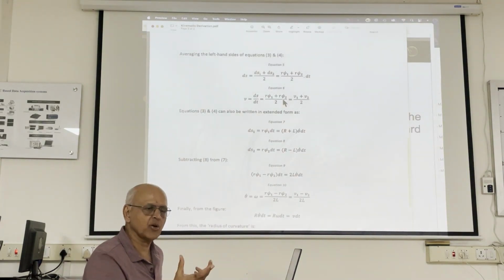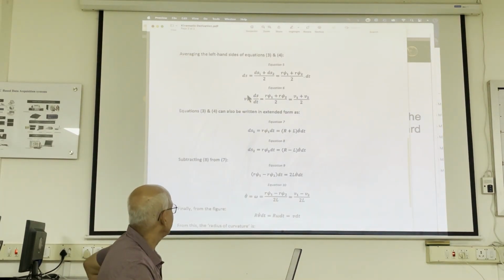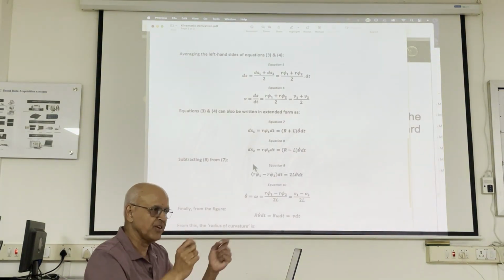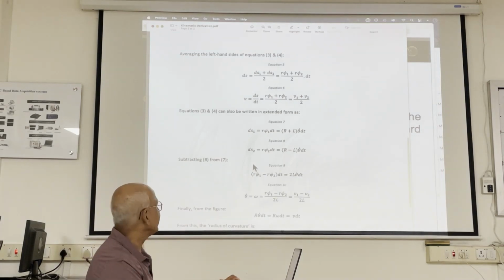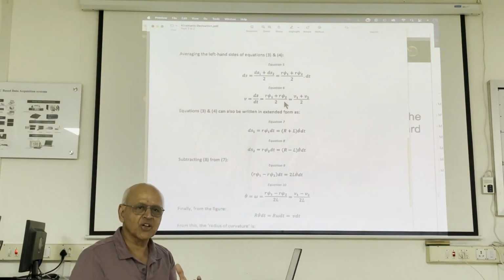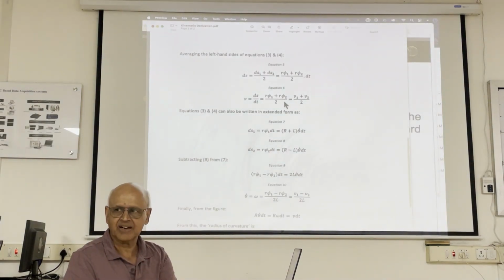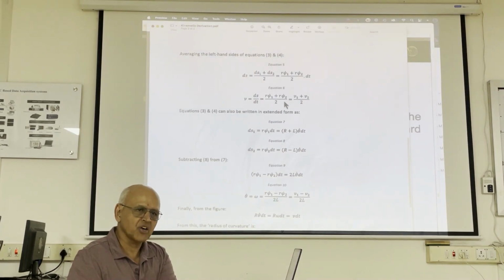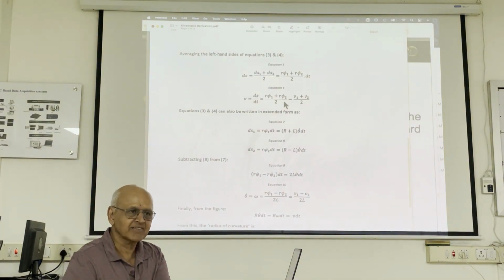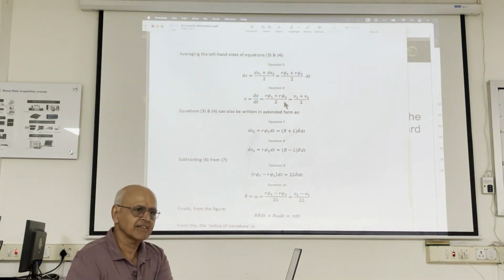It's a simple simultaneous linear equation. Given V and omega, the roboticist will say V, omega, and if I solve that, I can figure out phi 1 dot and phi 2 dot. And it is the job of the controller to create the phi 1 dot and phi 2 dot that give you the desired V and omega. That's not the roboticist's job. The controller takes care of that. Is that okay?